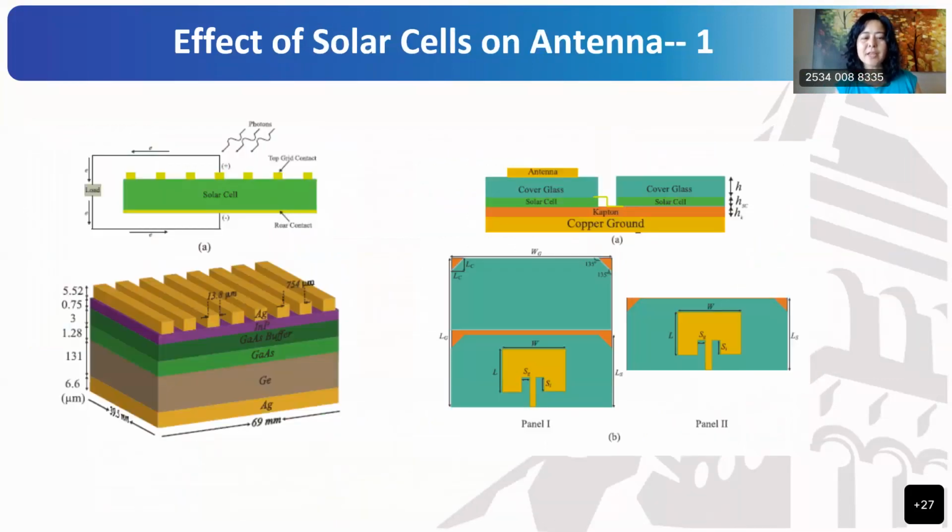All right, so the next page is to satisfy ourselves, to answer our own question as antenna engineers. How does the solar panel or solar cells affect our antenna? To do that, we put a commercial triple junction space certified solar cell under a microscope, and we used that to extract the layer information. So that's the information that I give you there.